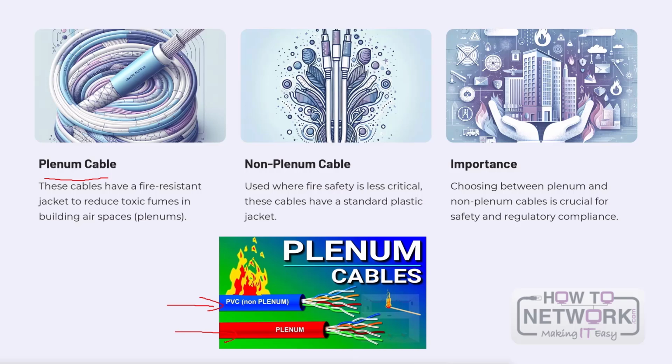So the selection between plenum and non-plenum cable hinges on safety and regulatory compliance. Building codes and fire safety standards often dictate the use of plenum cable in certain areas, ensuring the safety of occupants and minimizing potential fire hazards. And failure to adhere to these regulations can result in penalties and compromise safety.